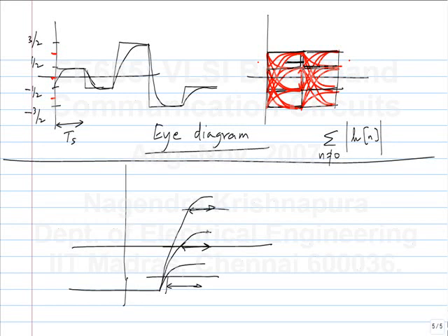Okay, let's say I want to receive this symbol, plus half. How would you construct a signal that has worst case ISI given the impulse response of the channel? You will give all of them the maximum weight with the opposite sign, right? You will make sure that in the convolution there is one term weighting the signal and all the other terms weighting other parts. So you just make sure that the weightage for the other parts is more.